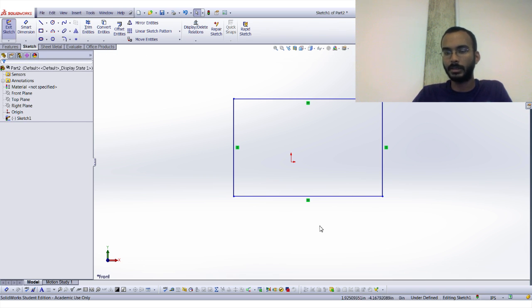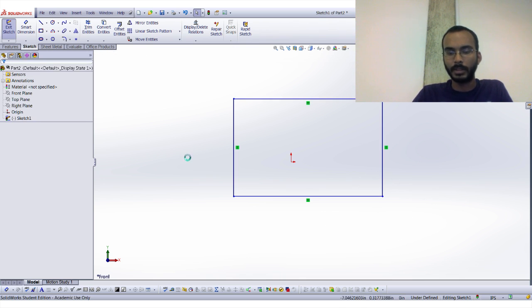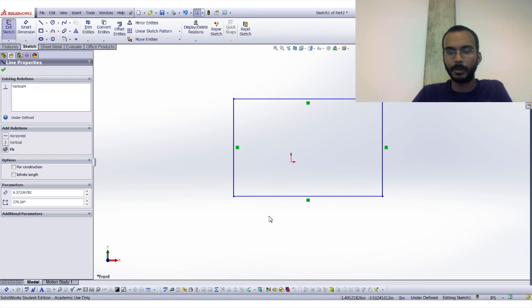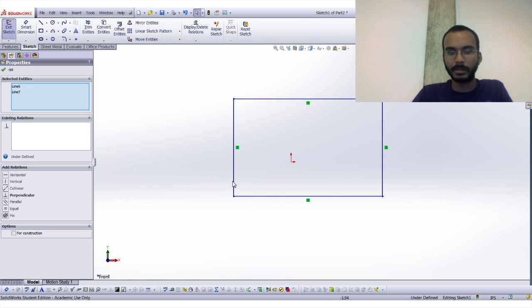It gives me a green box, and it selects everything that's partial. So it'll actually select all three things. So it ends up being really useful, depending on if you're dragging left or right, depending on how you want to do selection. So if you only want one side of this, it's far easier to drag from the right and grab the whole thing than from the left, where you might get 2 lines instead.